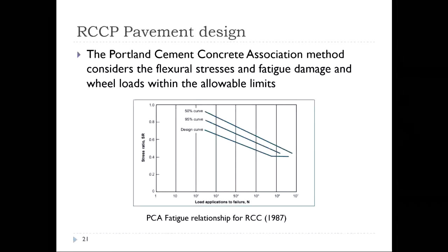Now these are the fatigue relationships given. If you look into the PCA fatigue relationship, you can identify the equations of these curves. Basically, this is the 50% curve, considering the best fit, where 50% of the points are above and below. This is the 95% curve, and this is the design curve. This is a more conservative fatigue design curve.